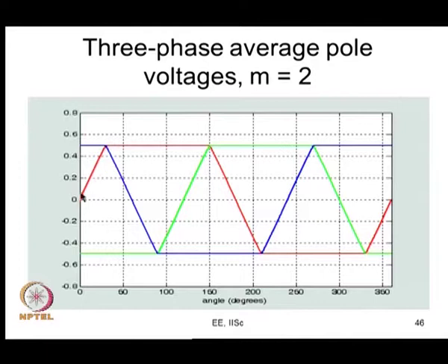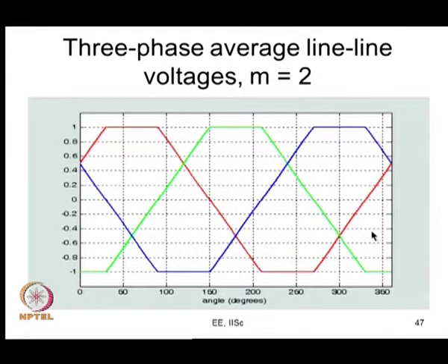So this will be evident from this figure. This is your VRO average pole voltage, and now this is your VBO average and this is your VRO average. They all look almost trapezoidal waveforms, because this is sinusoidal actually, but sine around the 0 crossing is more or less a straight line, sin theta is approximately equal to theta, therefore sin x approximately equal to x, therefore you get this kind of thing here now.